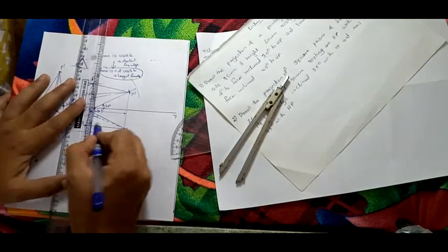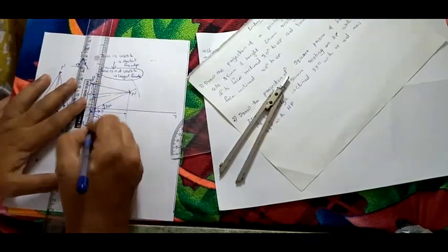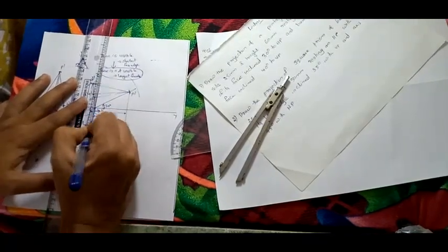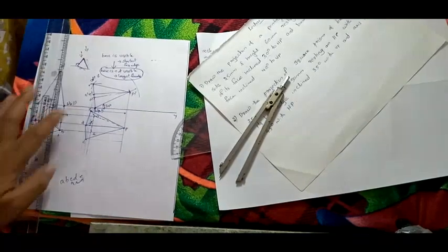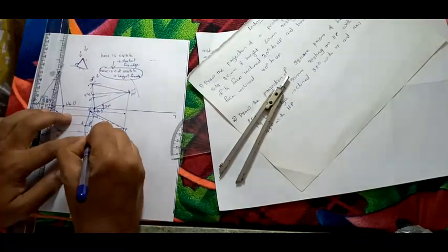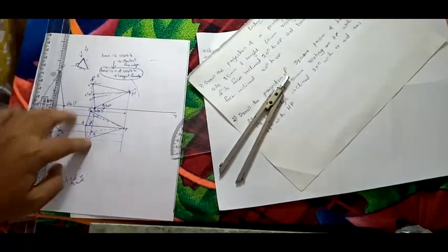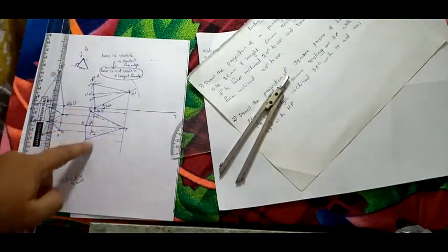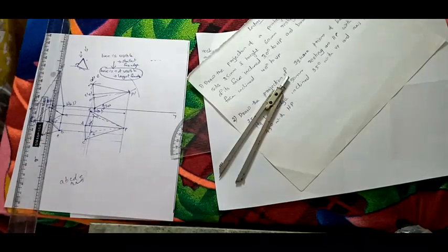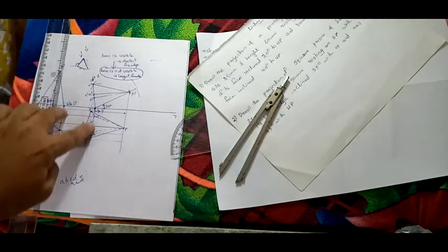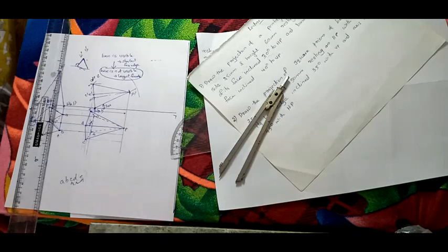Now the nearest is AB, that is also inside these two triangles. Half of it is inside one triangle and half is inside another triangle, so it is a dotted line. Now similarly join this with a dotted line. The last one is B, that is also inside this triangle, so these will be dotted lines, that is, invisible. You understood, right? So this will be dotted, this will be dotted. Why? Because we start from the largest face if the base is not visible. If the base is visible, we will see that in some other problems.